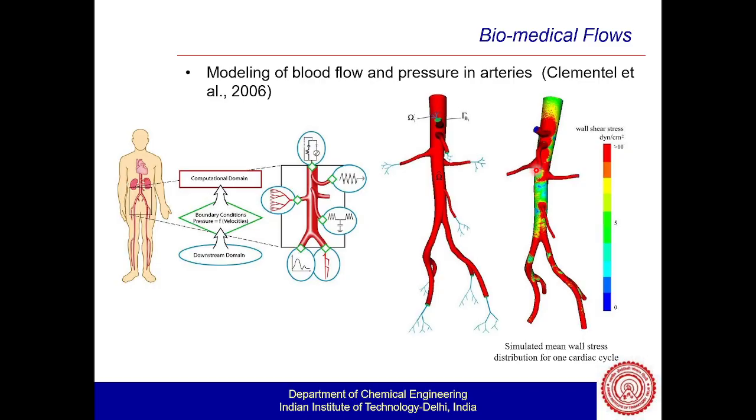Then I solve the Navier-Stokes equation and the continuity equation in each and every cell. For example, if it's a basic heat conduction in a solid, that will be the heat transport equation: rho Cp dT/dt equals k d squared T/dx squared, if it's a 1D transient heat equation. And if there is a source term, that will be plus S.